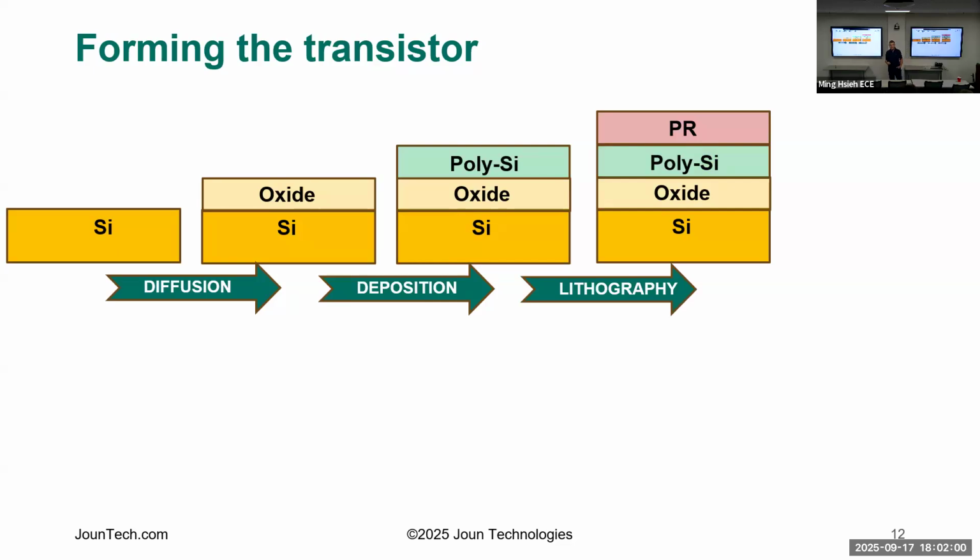It's called photolithography. And what it does is it basically is the step where you're going to transfer your design pattern down onto the wafer. So if you ever did stencils or stenciling as a kid, it's essentially a stencil process that you're using. And so there's something in semiconductors called a mask. And what happens is a mask is built from the design. So when you send in your CAD design, they build a series of these masks.